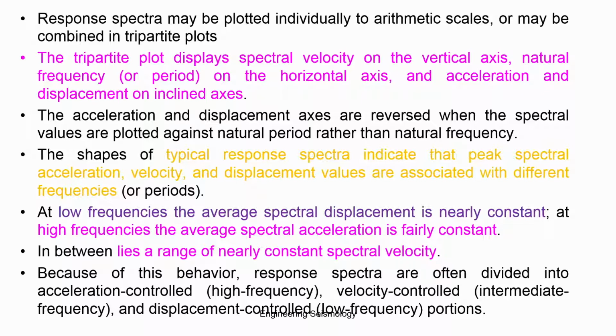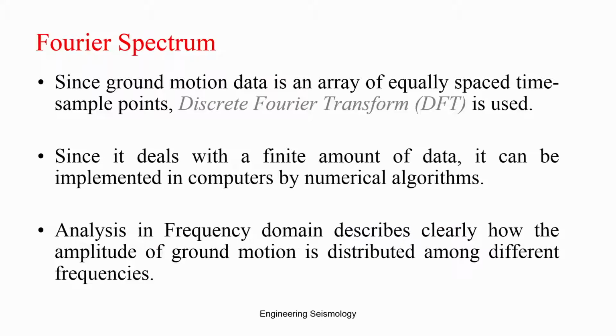The response spectrum is often divided into acceleration controlled, the high frequency range, velocity controlled, the intermediate frequency range, and displacement controlled, the low frequency range. So this portion comes in the tripartite plot and design spectrum development portion. You can discuss this in detail. So this is about the response spectrum.